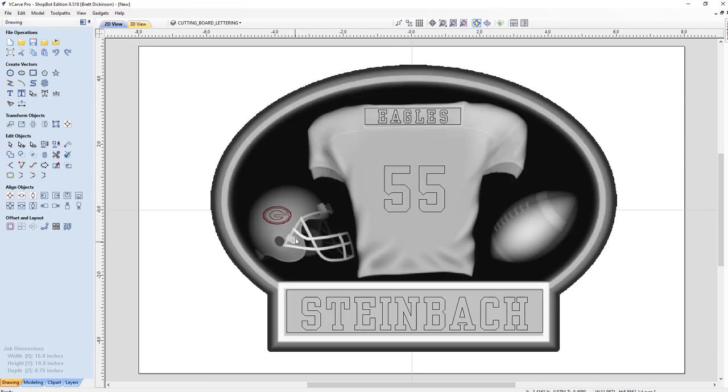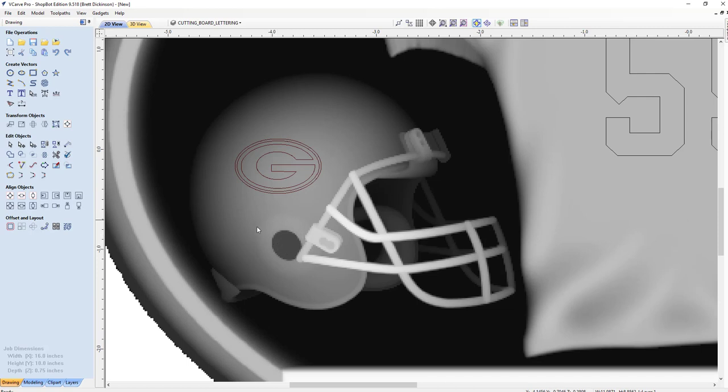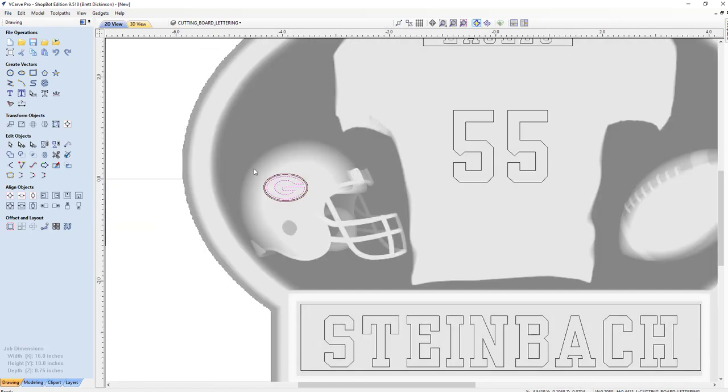Now click on the helmet because you'll see there are the face guard right there. And if you get a little closer, there's a piece of the helmet's going to come out right there around the ears. So we brought that in, but I want to make sure that that's grouped. And we press the G key to group, the U key on the keyboard to ungroup. It's that simple. So I'm going to make it as a little bit too large.